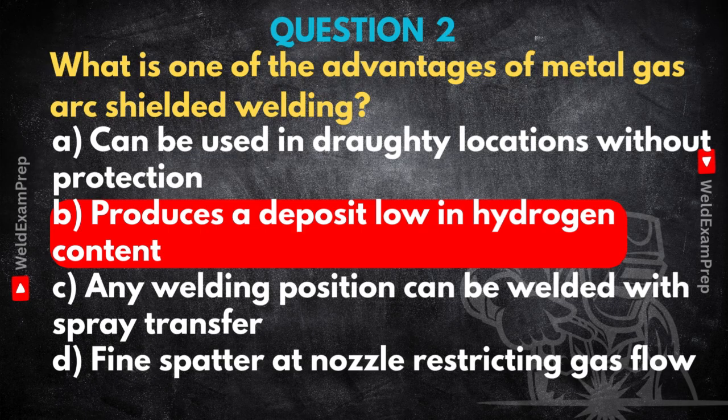It absolutely is too good to be true. While MAG-MIG itself is very versatile, it has different ways the metal transfers across the arc. Different modes, yeah. Spray transfer mode specifically uses quite high currents, and it produces a very fluid, almost liquid weld pool. It's hot and runny. Like pouring water almost. A bit like that, yeah. And because that puddle is so fluid, gravity becomes a huge factor. This generally restricts spray transfer to flat positions, like welding downhand on a plate, or maybe horizontal fillet welds. Where gravity helps you, or at least doesn't fight you.